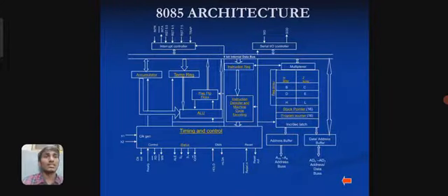So here you can see the complete 8085 architecture, which has the accumulator, temporary register, flag flip-flops, ALU, timing and control units, an instruction decoder and encoder, stack pointer, program counter, address buffer, and data address buffer, denoted A0 to A7 as we discussed earlier, and serial input and output ports, and interrupt controllers.